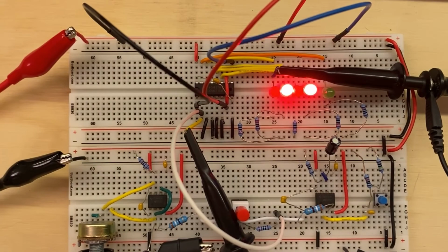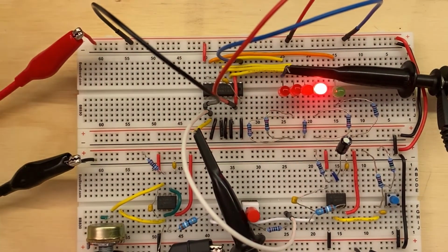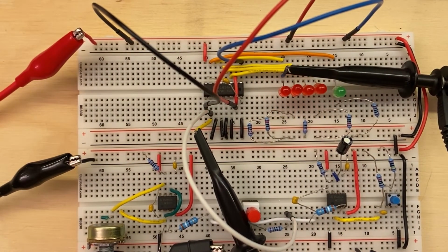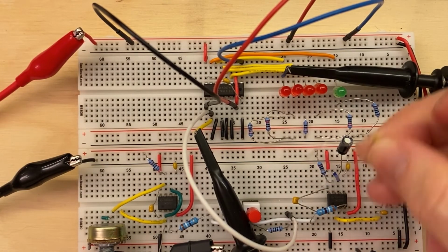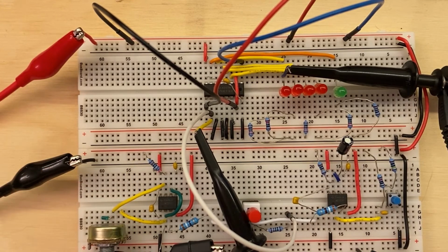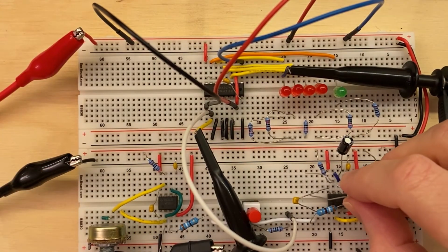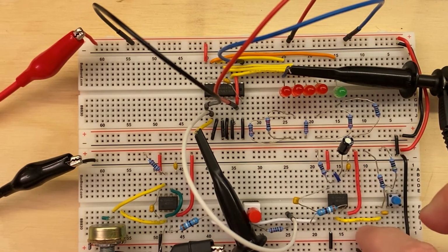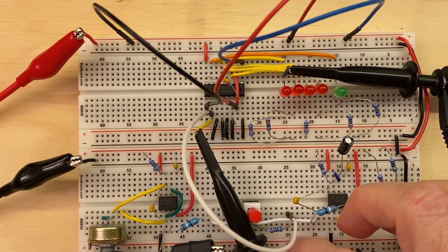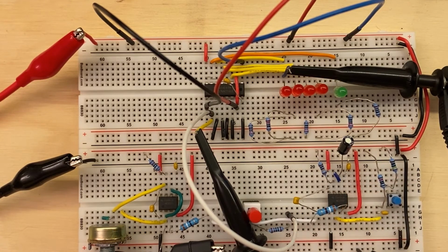But the truth is, and let's just turn this off for now, I have all these blinking lights. But the truth is that in our circuit, sure, this capacitor has been designed as one, but really, anytime you have metal close to each other, that's a little capacitor. And all these breadboards are just tons of little pieces of metal, all very close to each other, and it's called parasitic capacitance. And so the bigger our board gets, the more parasitic capacitance there will be.